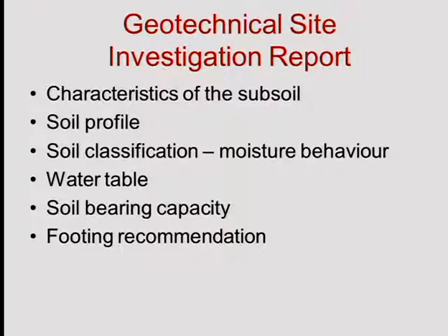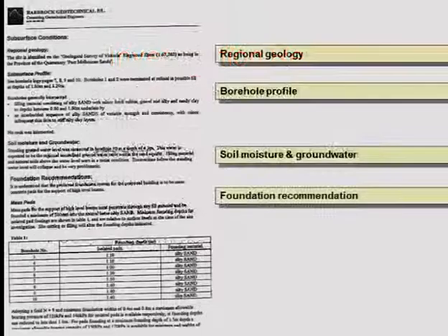It's very, very fine particles of soil, silt, completely surrounded with moisture, and it's got sulfuric acid in it as well. So it's almost the perfect storm of really bad soil down there. So it's far cheaper. In fact, it's almost impossible to excavate there. So you'll find all the car parks are above ground. So here's a direct way that the site is impacted on the design response.